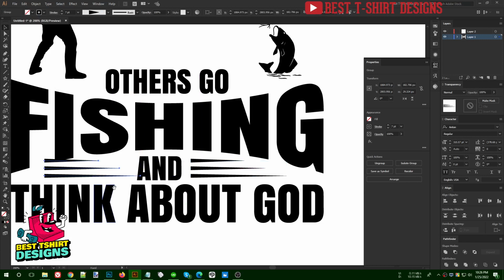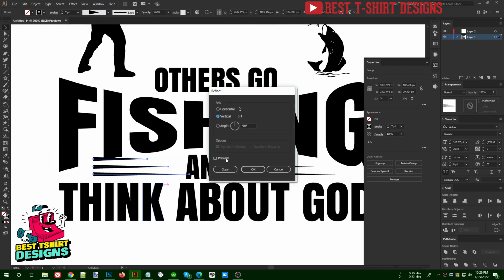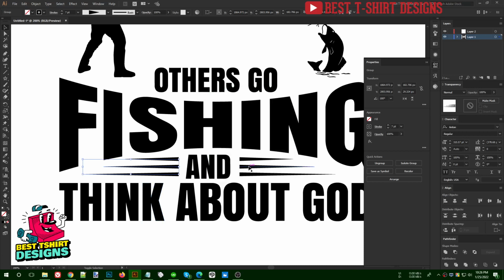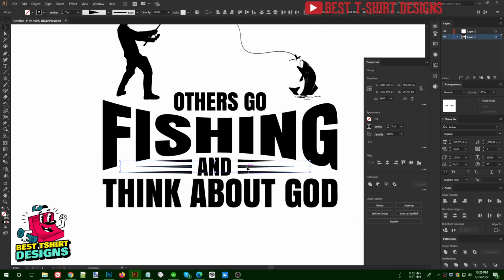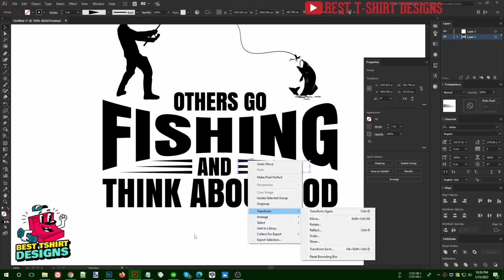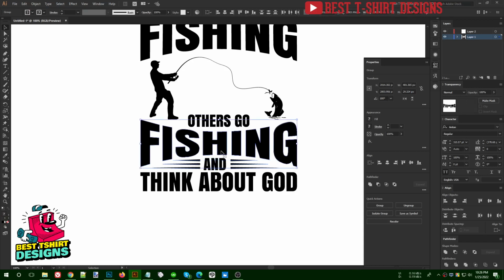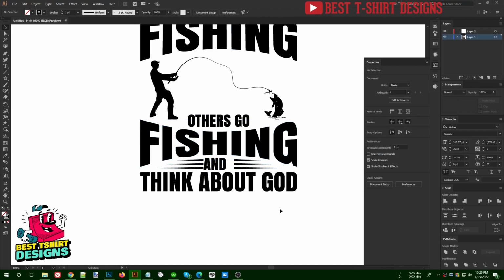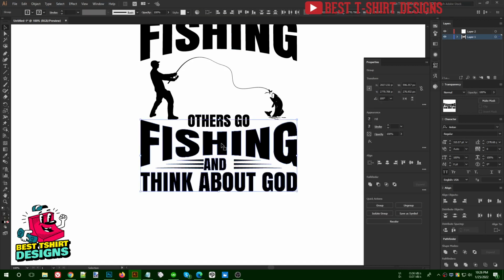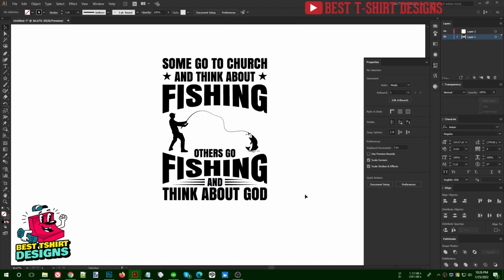Then again bring it on here by pressing Alt and Ctrl R for reflect. Okay, so Ctrl R is not for reflect. That is my shortcut. For reflect, you have to select anything, right click, transform, and then reflect. I have a video where I showed how to set keyboard shortcuts. Maybe you should watch that one first. Okay, so this is the center position. Now I'm going to select everything from this area and make this the key object. So everything else here will be aligned with that guy, and this is good.